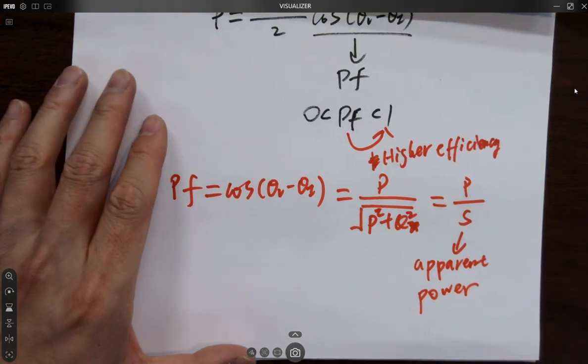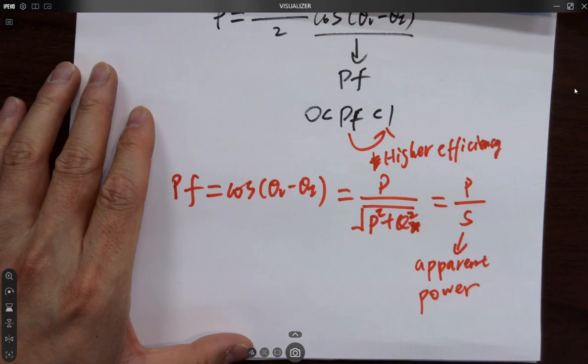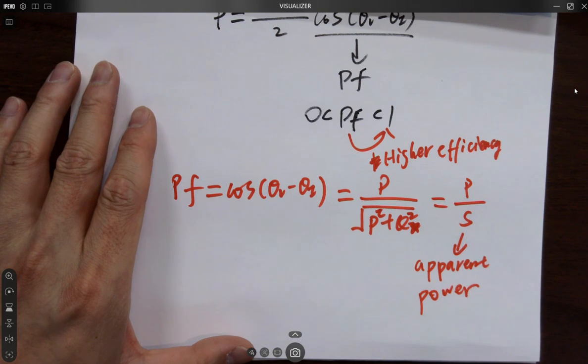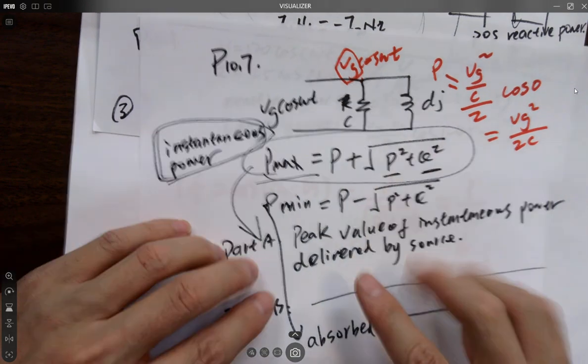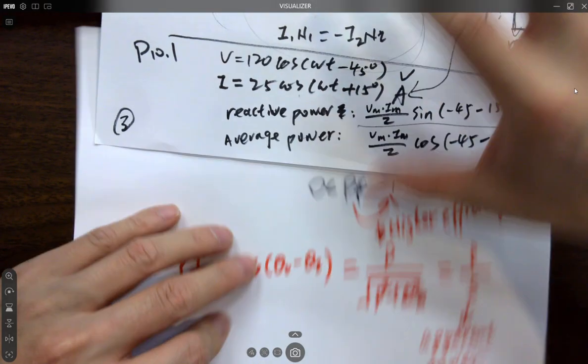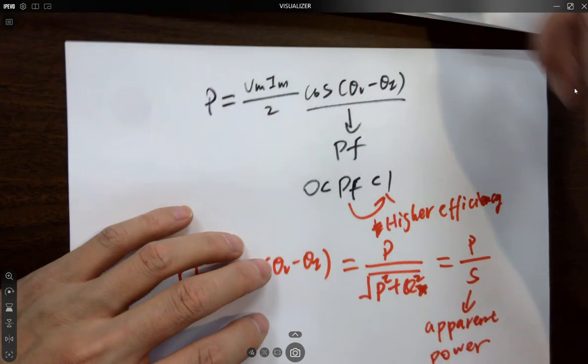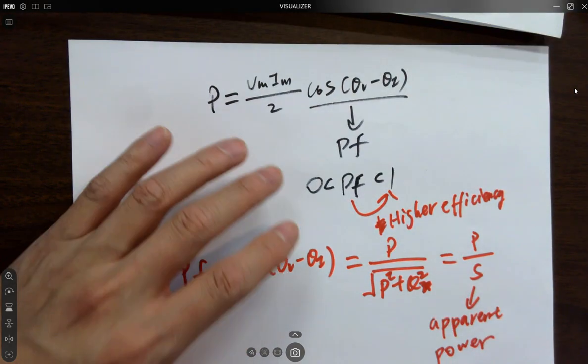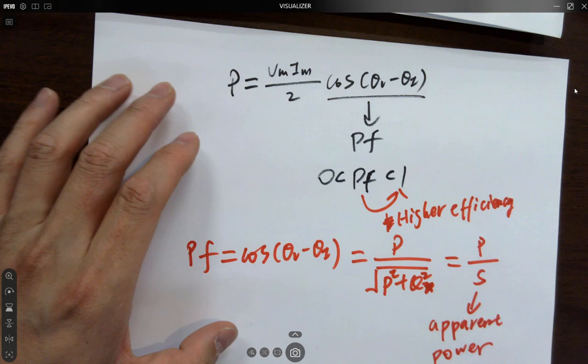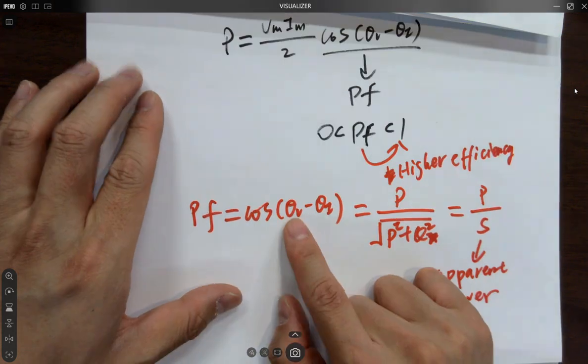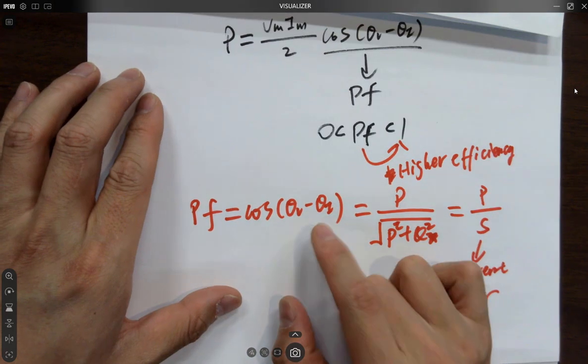Is the power factor a material property of the component? It's calculated by the impedance. It's an impedance phase shift, a cosine. Material, yes, because different inductors will give you a different phase shift, right? But eventually it's just the V and I phase shift, depending on the impedance.